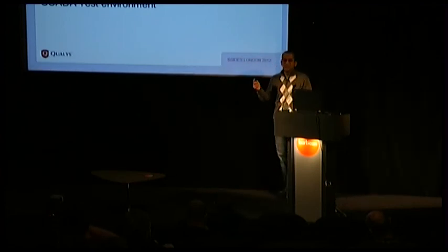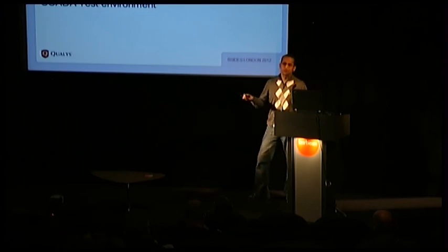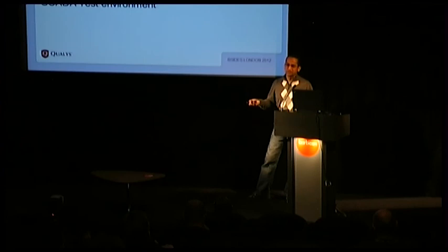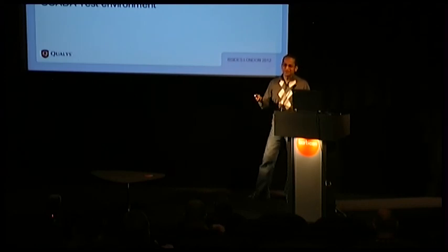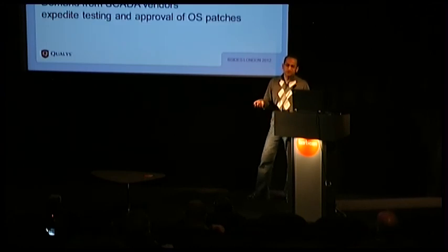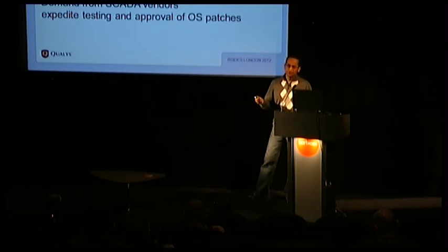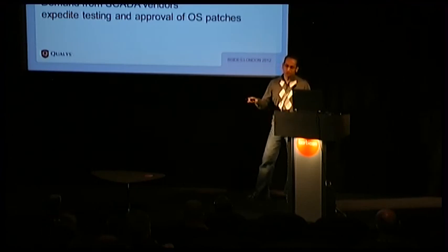And again, these are very easy proposals, easy for me to say. They are not by any means easy for SCADA system owners, because having a test environment which mimics at least half or 40% of what the real system does will cost you a lot of money. And getting those different approvals and getting a test system, if any of you maintain a SCADA system, you would know that there are very few people who actually have a test system where you can test out your patches or test out things before applying them to the SCADA network. Demand from your SCADA vendors that they expedite testing of various patches and say that, okay, this patch is safe to apply, go ahead and apply it, so that hosts are not left unpatched.